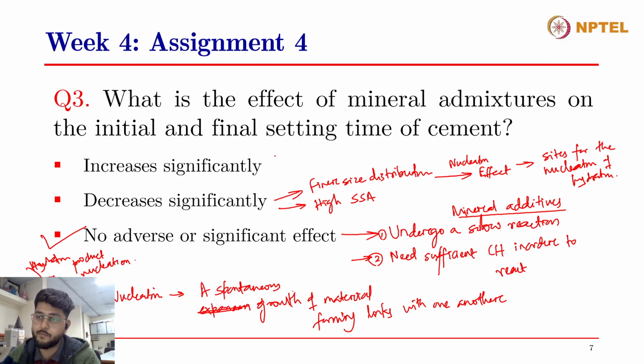If you replace the cement with mineral admixtures in huge quantities, they can, in a way, increase the setting time. So again, this is an indirect effect. They don't directly affect the setting time anyway. So indirectly,